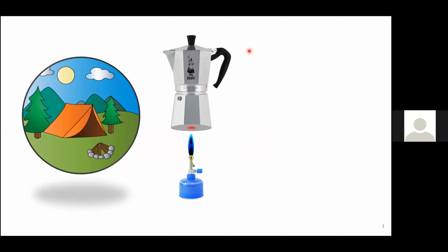So what happens is the Bunsen burner focuses to a small spot on your metal, and then the heat spreads, right? This process is on a centimeter scale and it takes seconds to heat up. In fact, this heat is diffusing with roughly 1 centimeter squared per second. So this is the diffusivity of heat in metal.